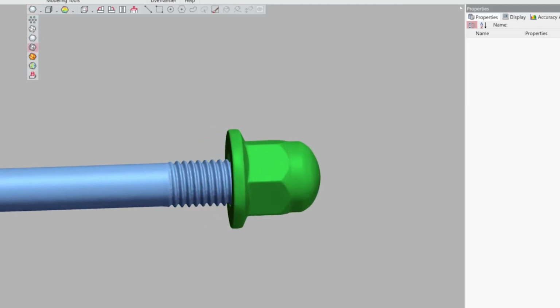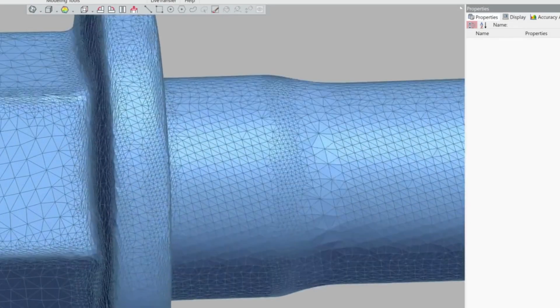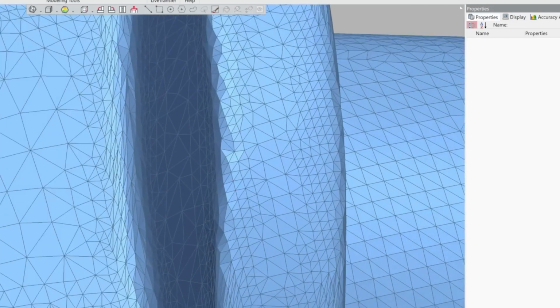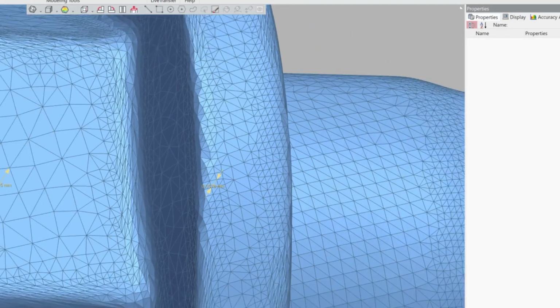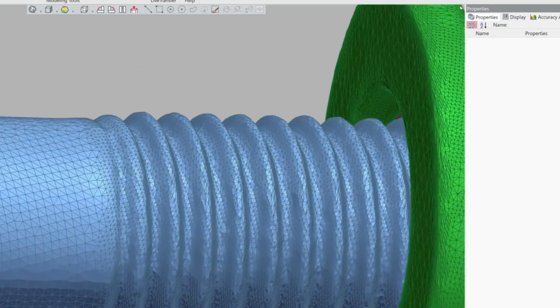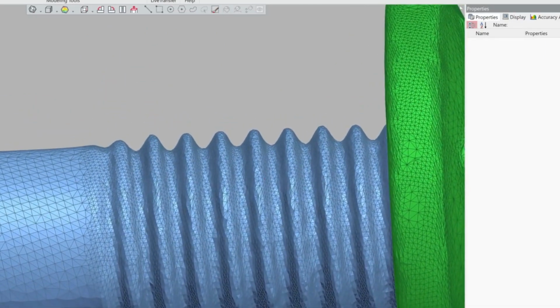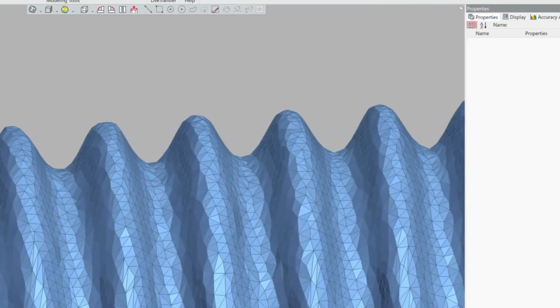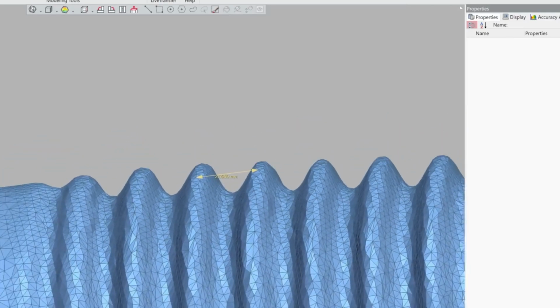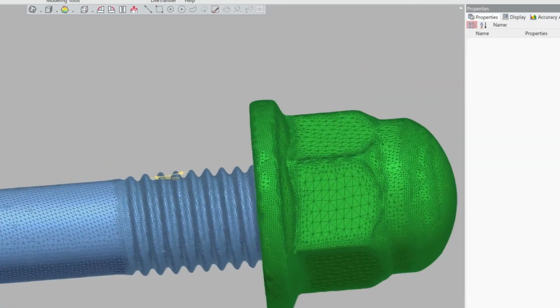So what you're left with from an STL point of view is every single one of those joined up to make a triangle, and you get something that looks like this. It's just a big series of triangles. If you zoom in enough, you can see them. The display setting you select here is going to be pretty important. But you can see here that this is what the series of triangles looks like, with a little bit of CAD smoothing in there as well.